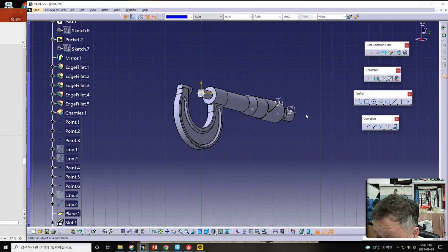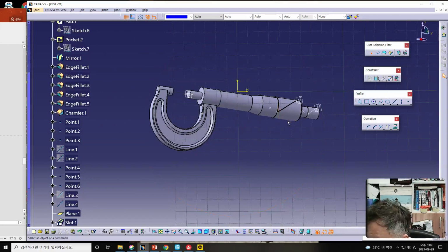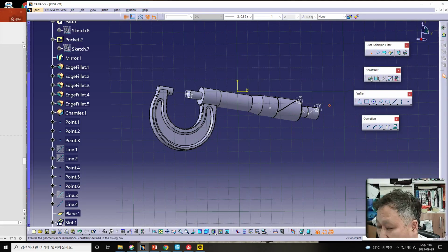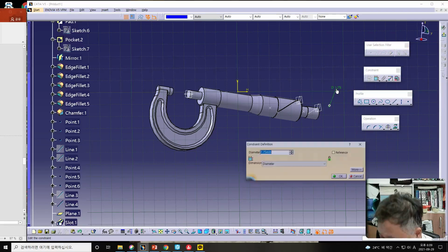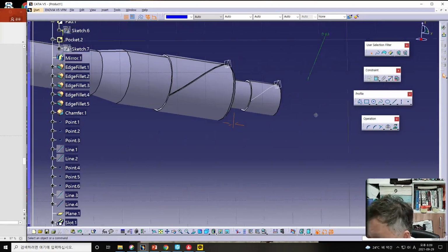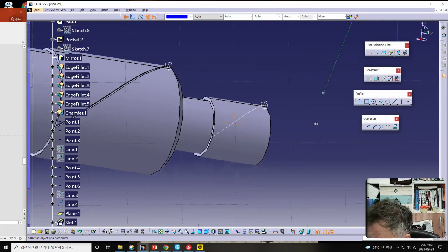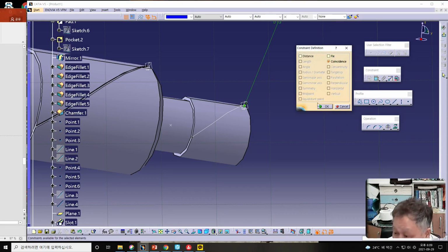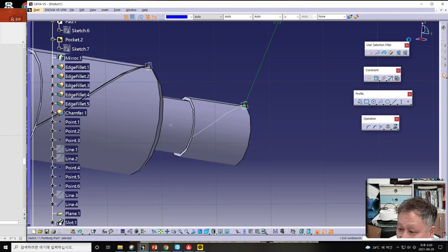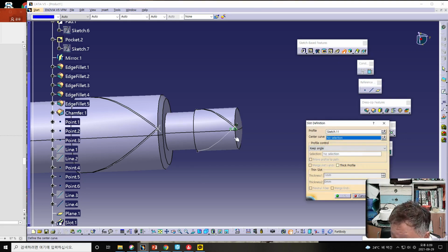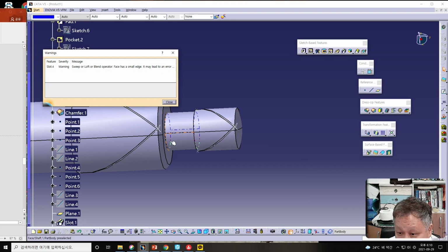click the point, and click the circle, and made some circle, and click the constraint definition dialog box, and the curve diameter should be 0.3 once again, and in this case the center point should be selected like this, and this one should have the alignment of coincidence by using constraint definition dialog box, and enter to the sketch workbench, and please select slot once again, and the center curve should be selected like this.